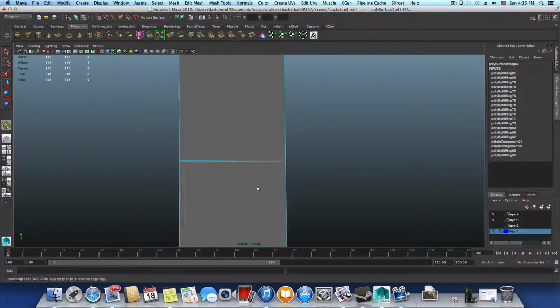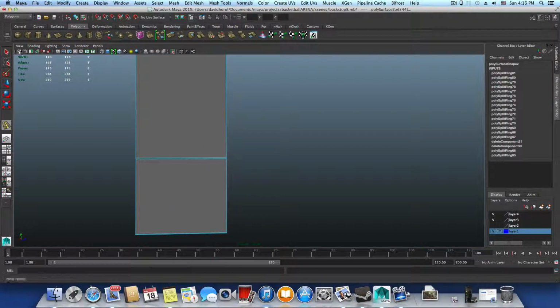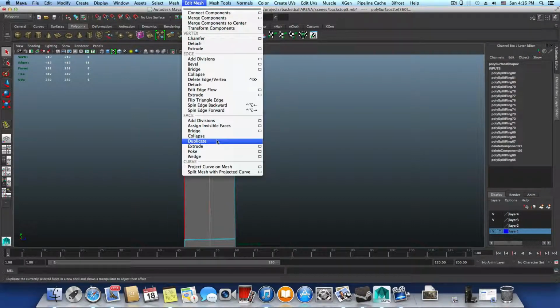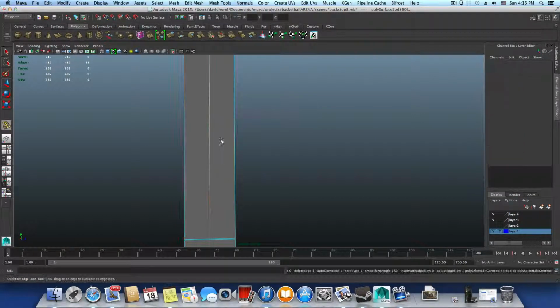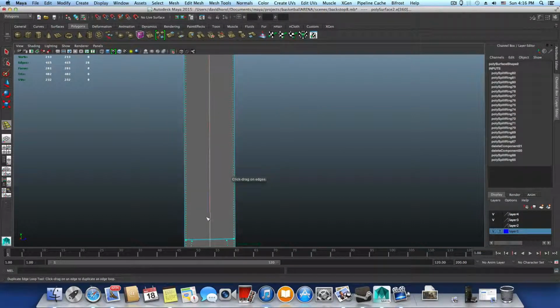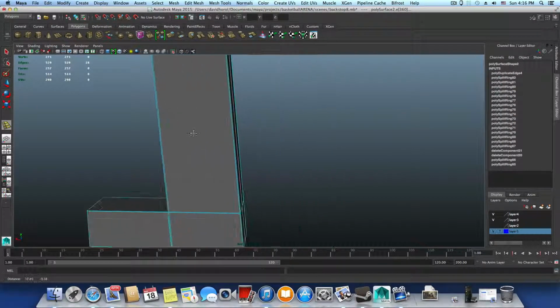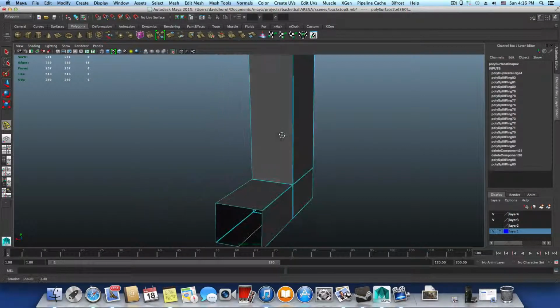Now I'm rotating the camera and I'm adding 2 more. So you can do this that way. You can grab an edge here, control right click, edge ring utilities, to edge ring and split, so we will have one in the middle. And you want to go to edit mesh, sorry, mesh tool, offset edge loop. Click here and add those two that way. Okay, so they will be equal in the distance between them. So this thing has been done.